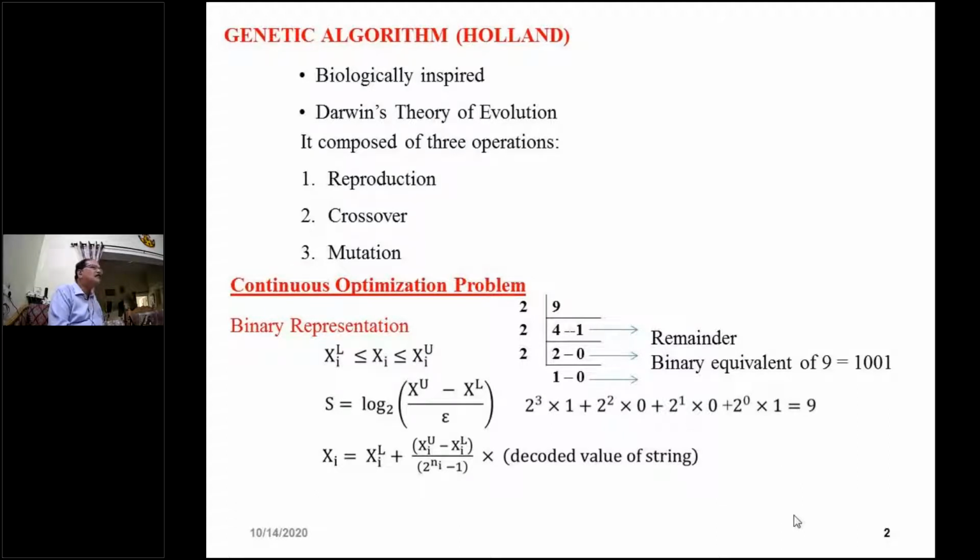The thumb rules are developed to solve a particular type of problem. Say Johnson's rule, which is applied to the flow shop scheduling problem, cannot be applied to the assembly line balancing problem or any other problem. In assembly line balancing, we use the rank positional weight method that cannot be applied to a scheduling problem. So heuristics are developed depending on the type of the problem.